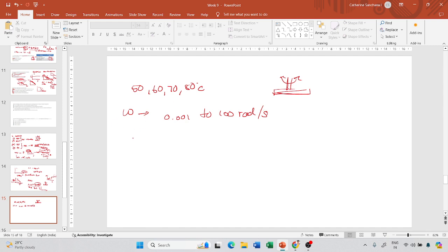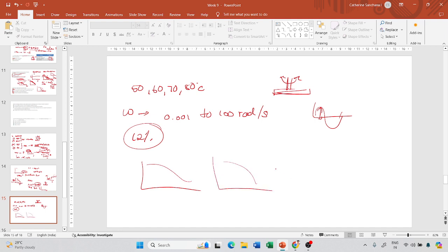And what should be the strain value? Since it is a sinusoidal loading, it has to have a frequency and a strain amplitude, right? So we apply a 12% strain amplitude, and then we will get 4 graphs, okay, for frequency versus phase angle at different temperatures, because we test at 4 different temperatures.